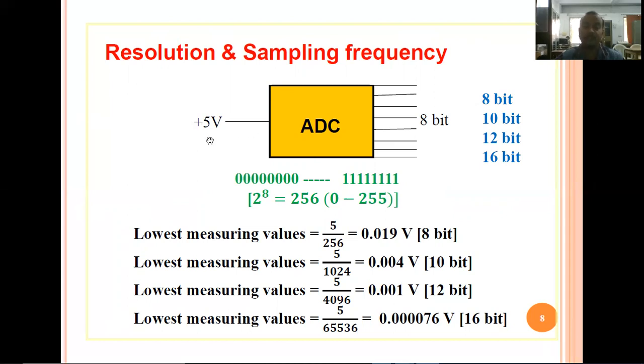If the information interchange does not happen at a similar speed, then obviously there will be a mismatch, a delay, a lag. So the sampling frequency needs to be adjusted for the processor as well as all the field instruments through which we take the information for control. That needs to be addressed for each and every case.